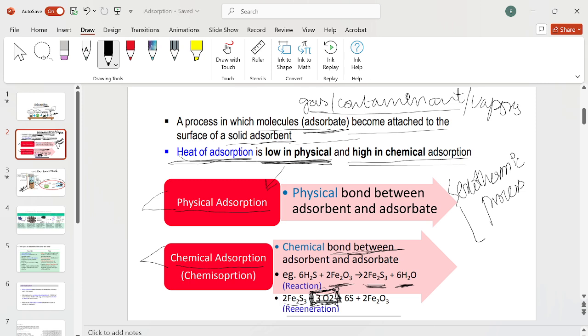You can see from here that heat is released. So adsorption is an exothermic process. If I give an example, a vapor is attached on the surface of a solid, and we are usually going from high temperature to low temperature, just like condensation, so that a certain amount of heat is removed in order to attach on the surface. So whenever the adsorption phenomenon occurs, there is release of heat. That heat is called heat of adsorption.